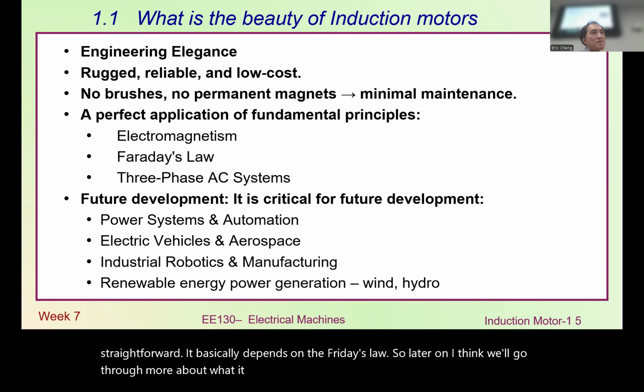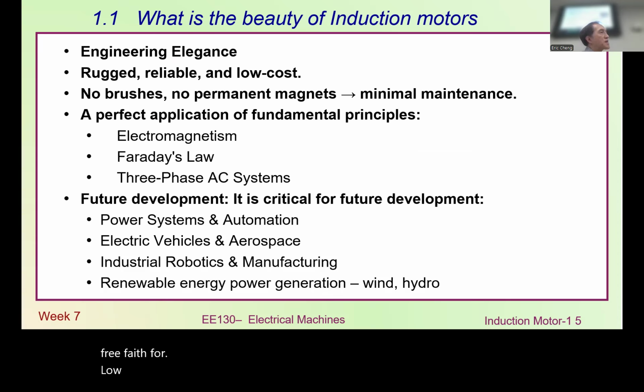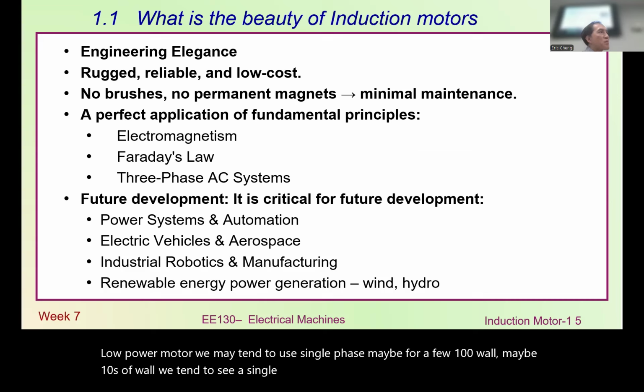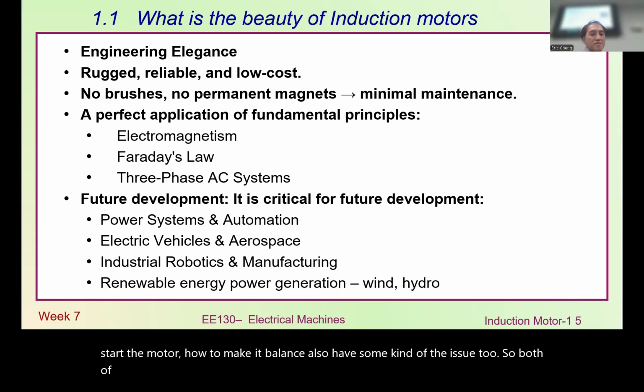And for the motor, we tend to use more three-phase motors because of three-phase balancing, and especially large motors must use three-phase. For low power motors, we may tend to use single phase, maybe for a few hundred watts, maybe tens of watts. But single phase does have some problems, like how to start the motor and how to make it balanced. So both of them will coexist.